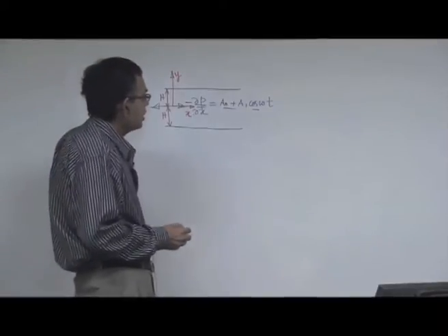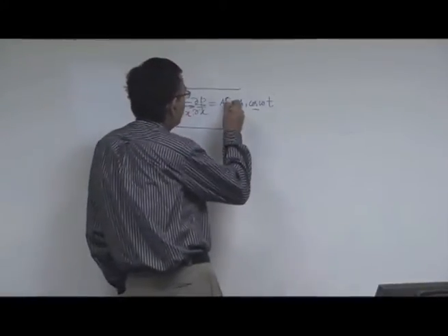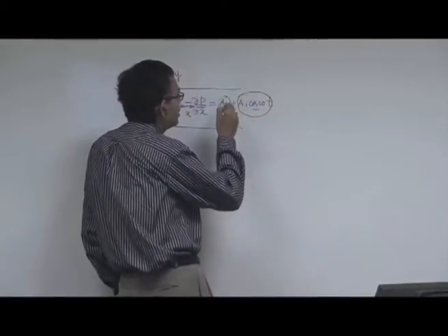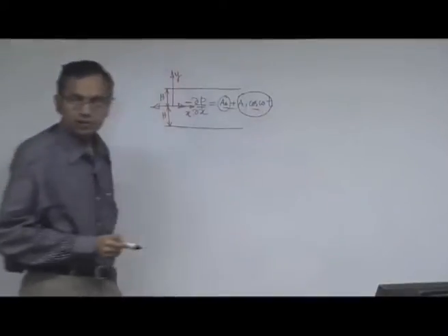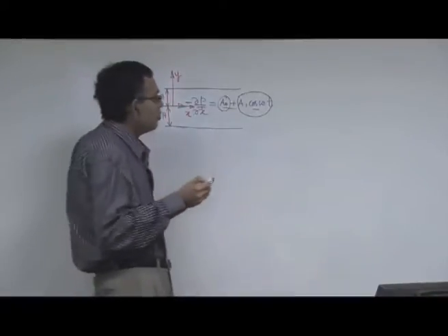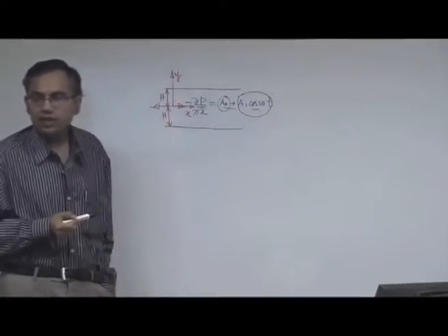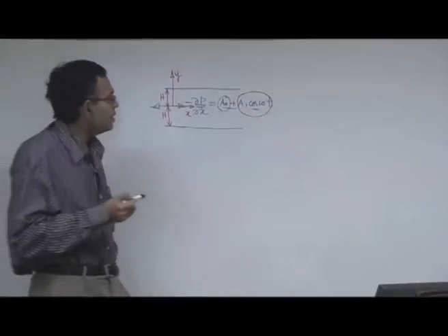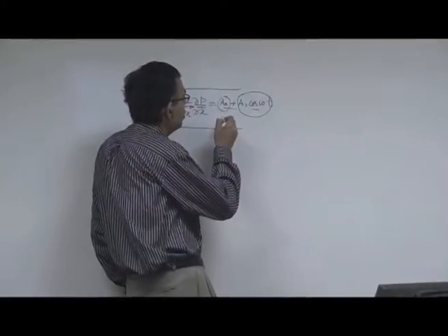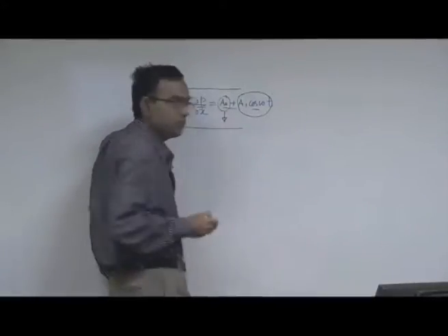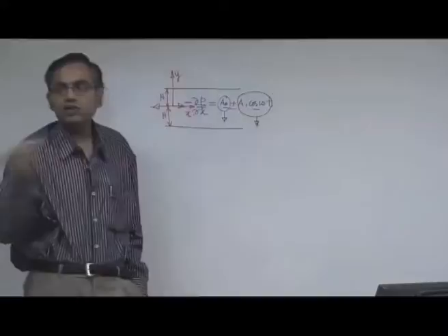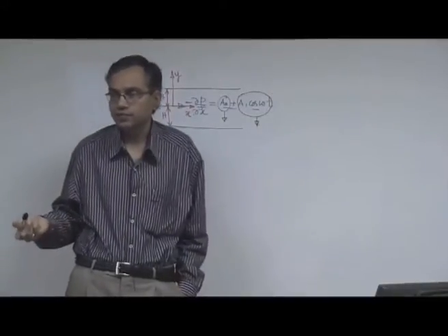Now, you can see that you have a pressure gradient which has a decoupled steady and time dependent part; they are not really coupled. So, that means we can exploit the linearity of the governing differential equation and obtain solutions for the velocity profile, one steady solution based on this and one unsteady solution based on this, and the net solution is a linear superposition of the two solutions. Okay.